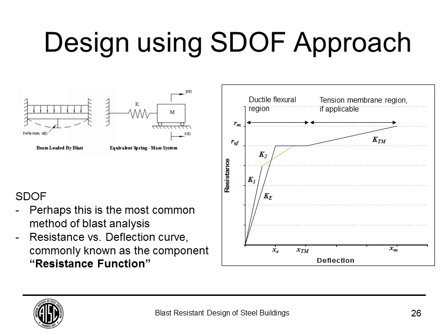In a single degree of freedom approach, we're simplifying the blast response of a member down to one mode of response. Hence, we call it single degree of freedom. If you're looking at this fixed beam right here, once that beam gets loaded by blast, it's going to want to bend as is shown right now. It might try to shake in shear. It might try to twist. It's going to have different modes of response.